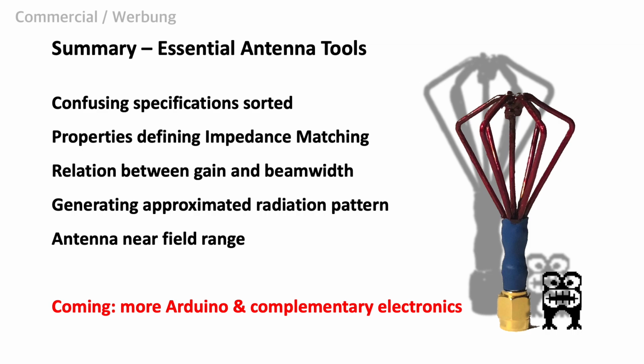In order to optimize the performance of a wireless system, we can find an optimum down tilt for a directional antenna. The range and the interference level can be improved so that your Wi-Fi connection, for instance, gets more stable. Antenna radiation diagrams are usually defined and measured in the far field. We learned how to calculate in what distance we can expect the far field.